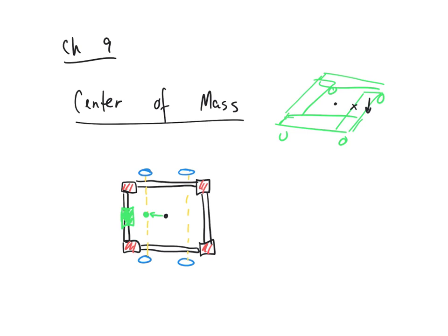We start to push this side, and keep going, keep going, keep going. And there it goes. And it's about where you expect. It's about halfway between this direction. So the direction that you're trying to find the center of mass in, push in that direction. If you're trying to find the center of mass this way, you push along that direction. If you're trying to find it this way, push along this direction. And as soon as it's about to tip over, you're at the center of mass.